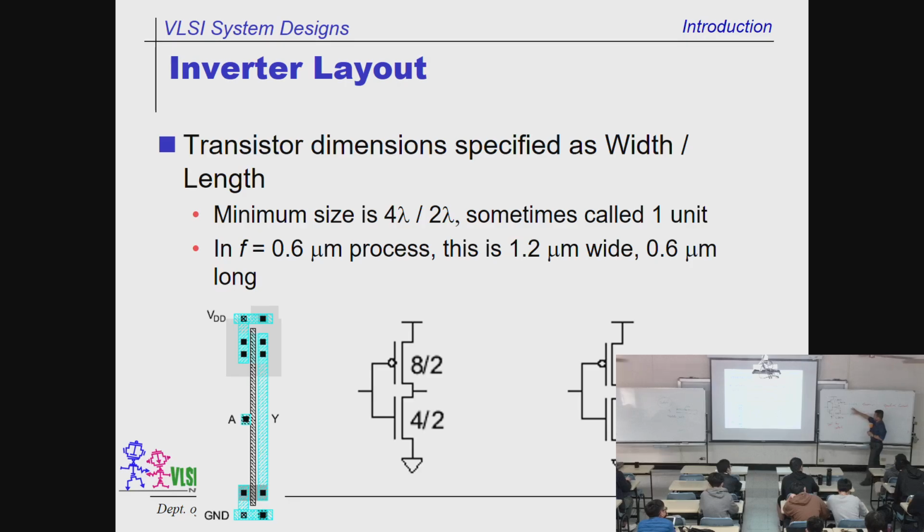If you have a bigger current, we can charge this faster, right? If you want to charge it slower, we can use a small current. So the current is like a hose. It is slower. That's why we have to magnify the size of the PMOS transistors so that the charging time will be equal to the discharging time given by an NMOS device. That is why we need a wider device on the top close to the power supply.